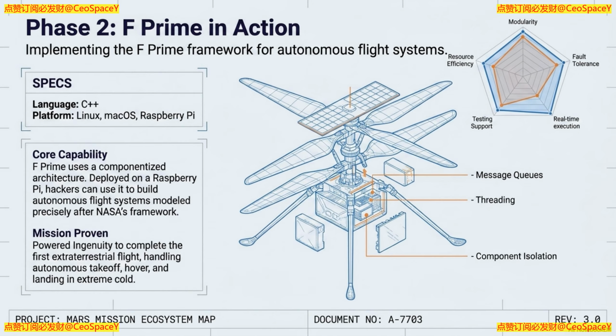Right, the cosmic rays. Yes, high-energy cosmic rays will literally strike the computer chips and flip the ones and zeros in your memory. So CFS is heavily verified and written in older, highly tested C code because it has decades of flight heritage proving it can survive those high radiation environments without crashing. It's bulletproof, or radiation-proof, I guess.